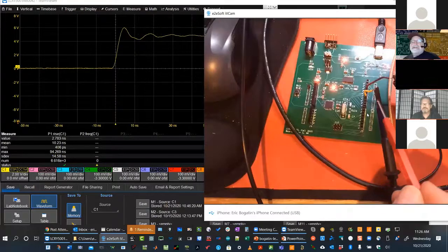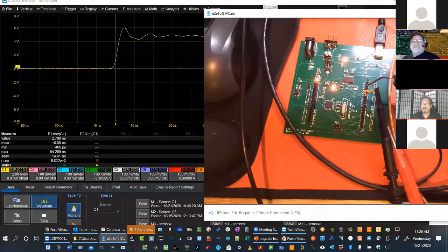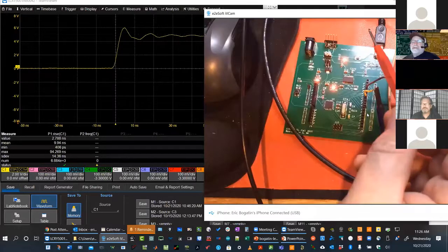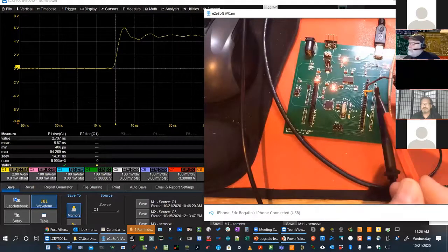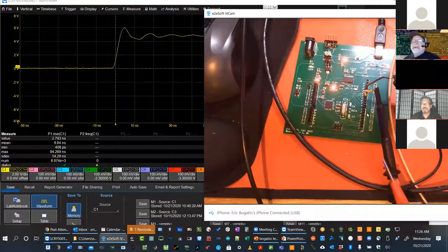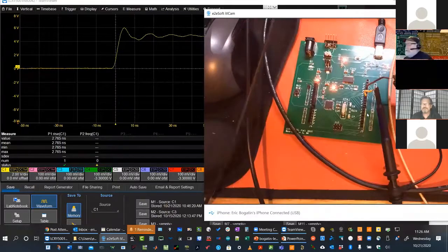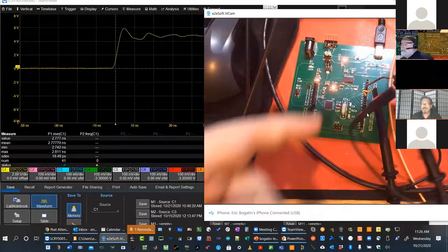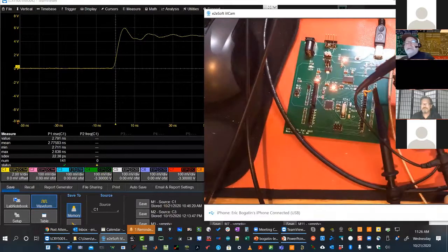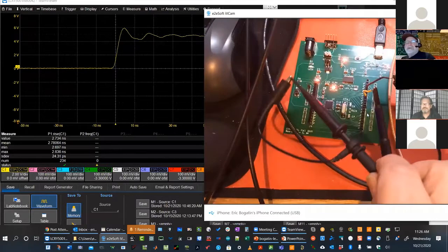The equalization circuit. And so we could get milliamps of current, especially for a fast edge, circulating in that loop. It's radiating. The impact of that is if we have another 10x probe, so here is another 10x probe, and we happen to be doing a measurement nearby, for example a crosstalk measurement. We say, how much crosstalk is there from another pin over here?